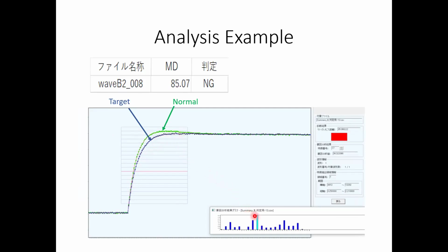Cause diagnostics indicates that the rise of the waveform is beginning to slow relative to normal in this part. The motor load may be starting to increase even though there are no people on the escalator.